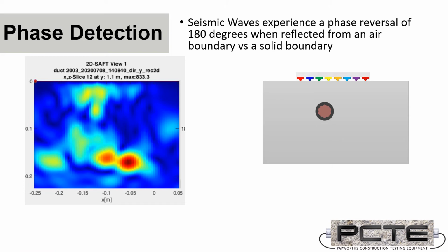Now, just before we begin looking at data from grouted ducts and ungrouted ducts, I want to look at a single B-scan and evaluate the shear wave energy in that B-scan. In particular, a single measurement was taken over the grout duct, and we can see, as in the drawing, the rebar with full grouting, unvoided grouting, and then the bulk of the concrete material.